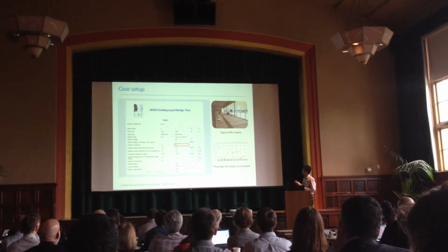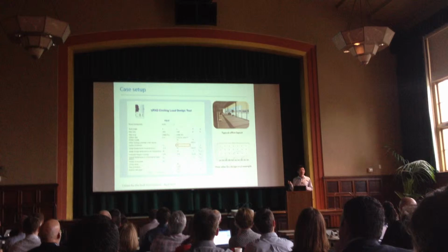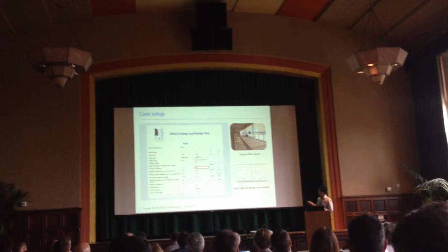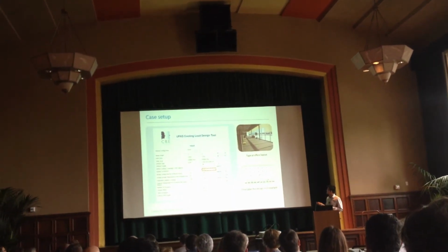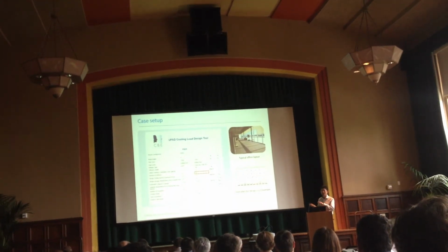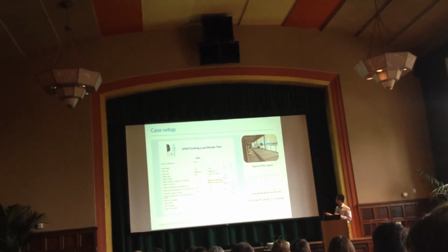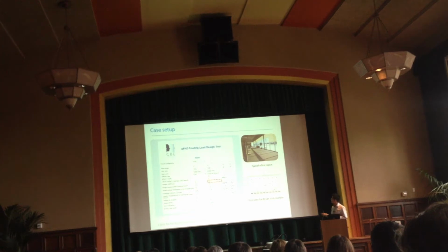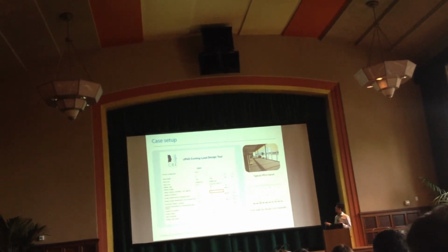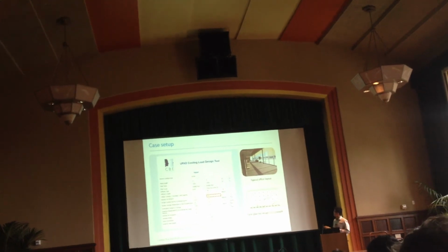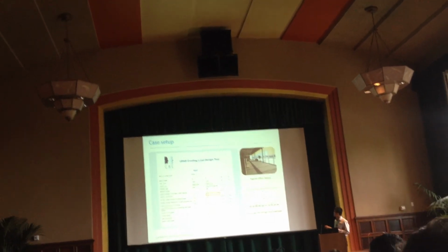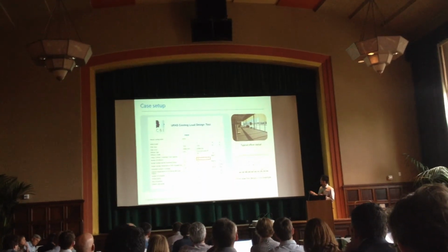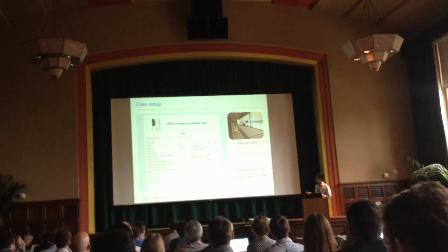It is a typical office layout with 5,000 square feet, two zones, both interior and perimeter zones. So for the interior zone, we use a swirl diffuser, and for the perimeter zone, we use the linear bar diffusers. And it is a series plenum, so there's going to be a temperature rise when it enters the perimeter zone. Right? And there are 20 people working in the interior zone, and this is a typical design cooling load for an overhead system for this office. In terms of the number of diffusers, we're going to start with 10 diffusers in the perimeter zone to see what's going to happen. So after we get all those inputs done, we hit the submit button.